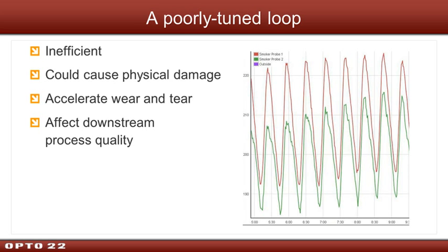It was controlling a steam valve for a heat exchanger, and it basically was just out of control. It was going from 100% open to 0% to 100% to 0%, and because the steam has a lot of energy in it, it was cracking and banging and causing the condensate pipes to rattle so much that the physical mounts of that pipework and the steam valve into the cement wall were actually cracking, and it was causing leaks in the system because it was banging that much.